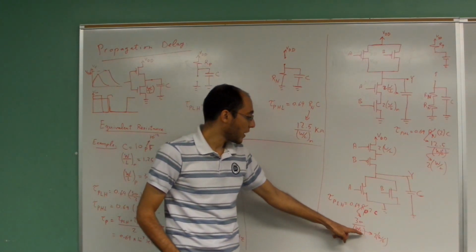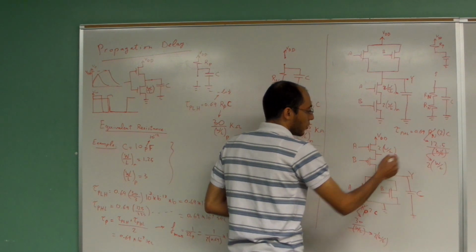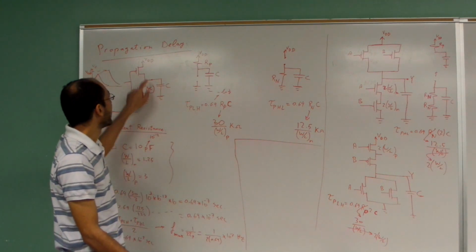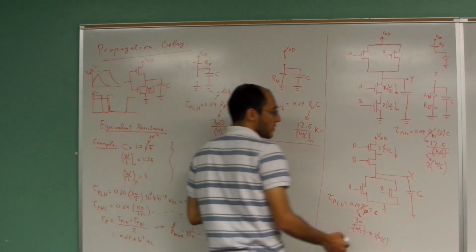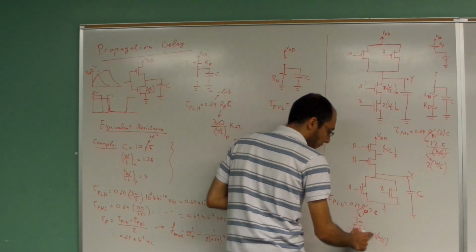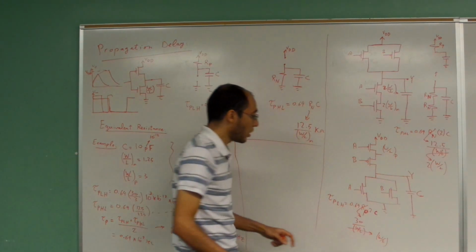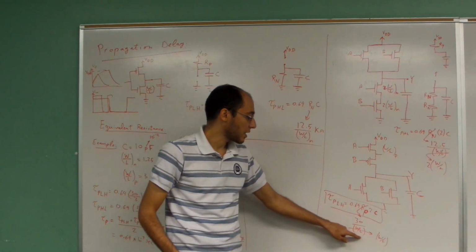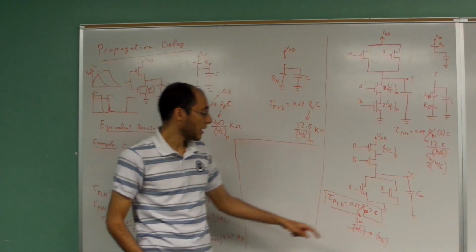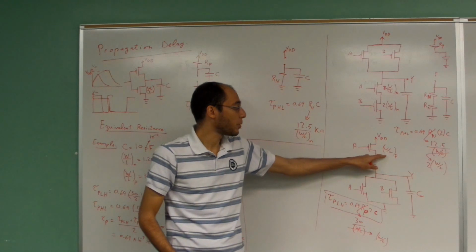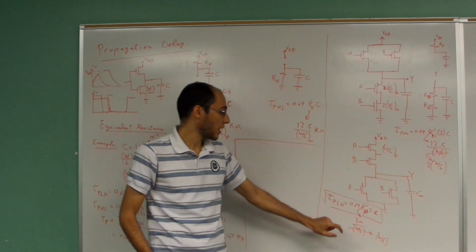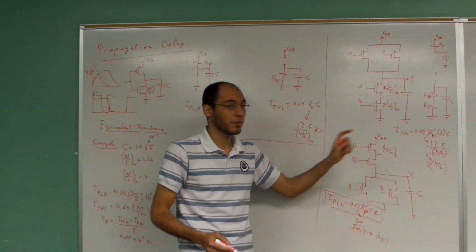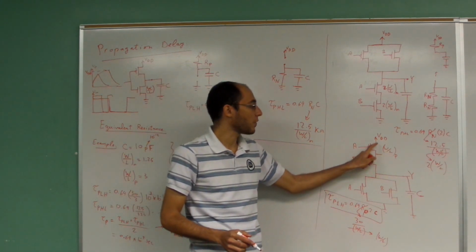So, if the W over L was not equal to 2 multiplied by W over LP, which is that of the MOSFET transistor of the NOT gate, then in that case you do not divide by this value. Right? So memorize this formula, and whatever the W over L that is given in the test, use that particular value. If it's properly chosen, then substitute by the properly chosen value. If it is not, then substitute by whatever value it is given. So the bottom line, substitute by whatever value it is given.